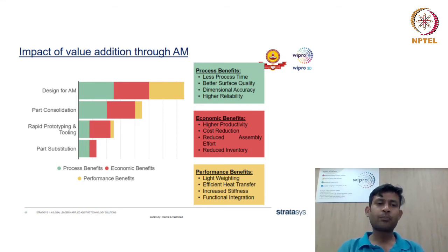If we are designing our components with the orientation of printing, the machine, the blade, the base plate, the whole environment known to us, then obviously we will be getting a higher reliability in our AM manufacturing process. There will be fewer build failures, and then there will be a minimum, an optimized cost associated to the manufacturing process.